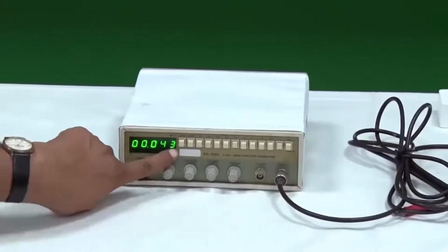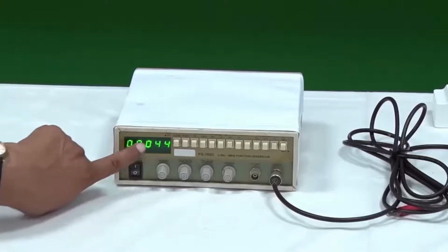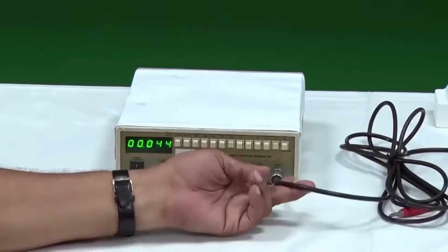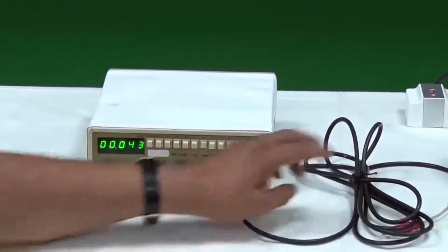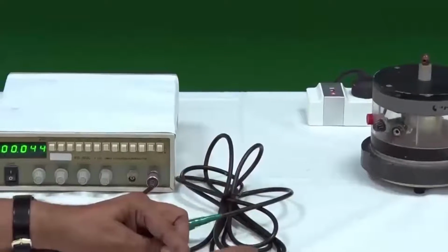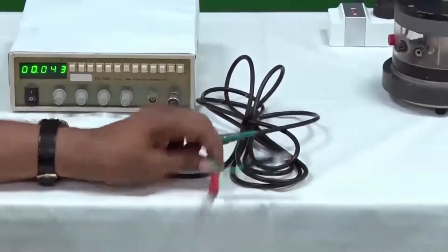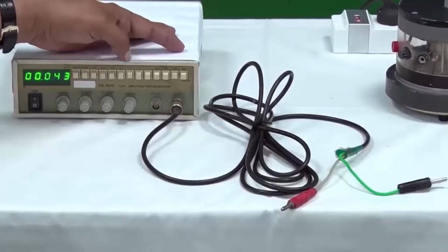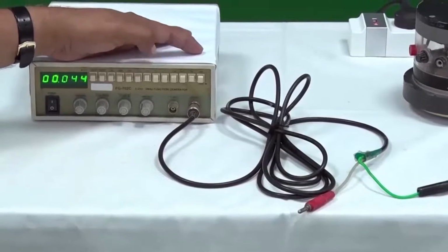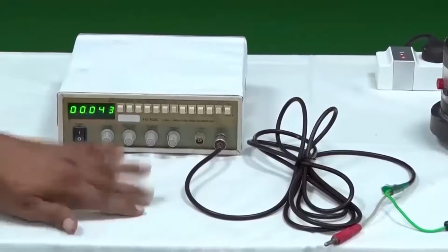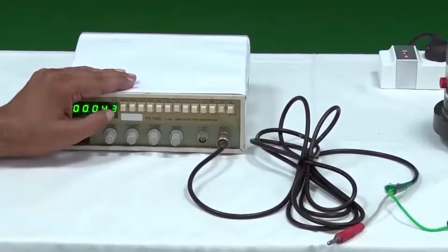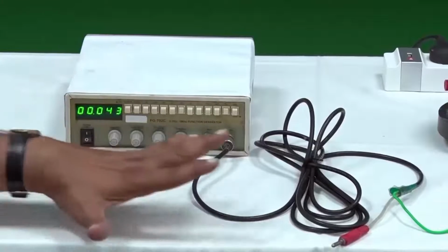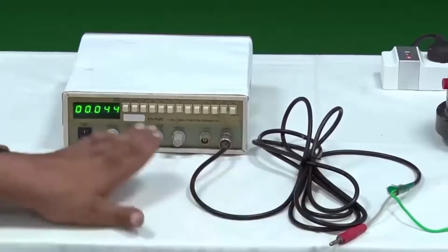So, if I put it on, you have this display which tells how much frequency it is generating. It is generating AC voltages, and that AC voltage is coming here. This is the output point, and finally these are the 2 points. So, here that AC voltage is coming at that frequency which is desired. The frequency can be selected, the various ranges are here. This is at the range of 100. Actually this time the frequency is 43 point something. So, it is showing 43 or 44, that many hertz, 43 hertz.